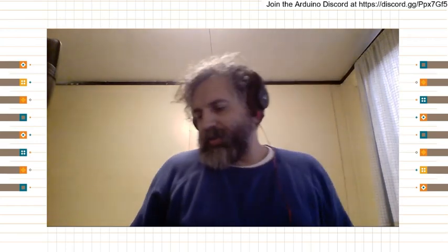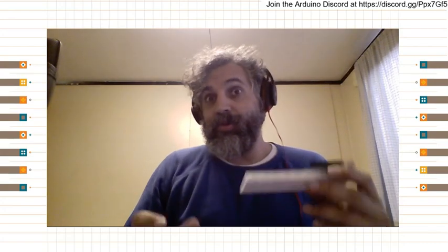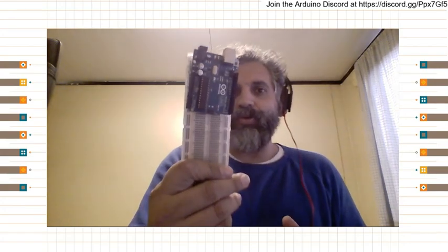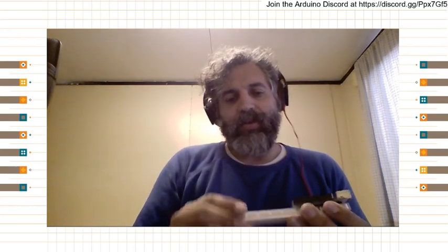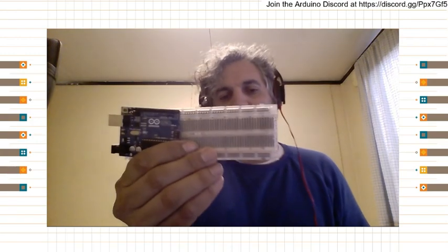So I'm going to show you one of my tricks that I use at the university many times, which is, if I want to not lose the boards from the breadboards, I glue the boards to the breadboards, like in this case. It's done with a bit of double-sided tape. So for a lot of projects, it gets very practical. So I can very quickly mount stuff.